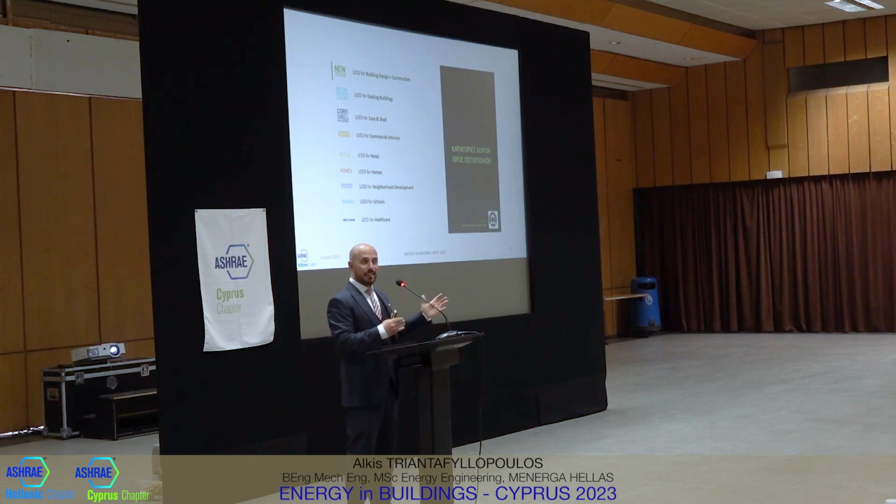So these certifications are important for two things. They're important for the end user because it gives them a certainty factor that this design is well built, the HVAC is well operated, is very well designed, and is above minimum. For example, if you want to have a LEED certified building, usually even your ventilation rates, for WELL or for LEED or for anything else, are increased, and you know that the thermal comfort is increased, the energy consumption is significantly decreased. So either you're an end user and you're occupying the building, or you're someone who's going to buy a house, or rent an office, you're going to have your utilities decreased. So there are a lot of win-win situations in those kinds of buildings.